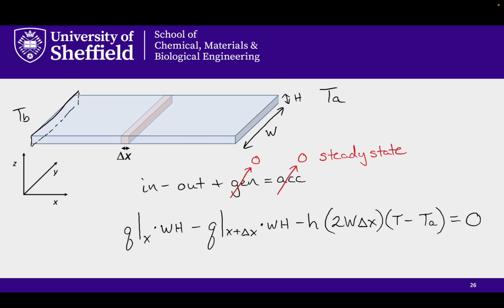And this is a good approximation, it works. And finally, our temperature difference, our gradient, is going to be the temperature, which is going to be isothermal when the shell is infinitesimally small. So it's whatever temperature the shell is at, T, which varies, minus the ambient air, because it's always convecting from the fin into the ambient air.